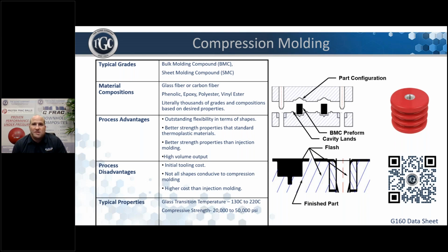Some of the disadvantages: although the longer fiber has benefits, it can be harder on the manufacturing process and add additional steps such as preforming materials. Another factor is also the tooling cost. Molds are typically a higher capital investment compared to other options. Not ideal for smaller production volume parts.